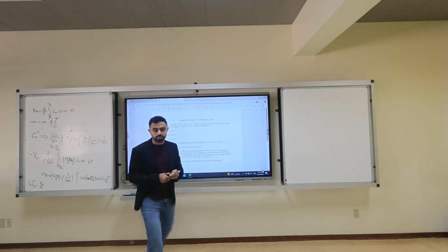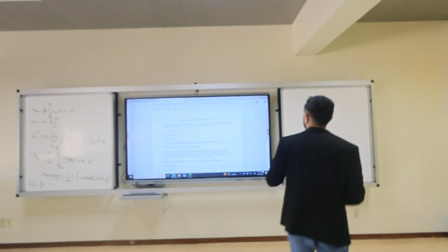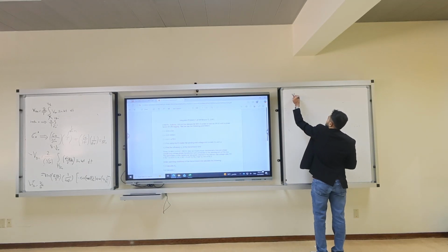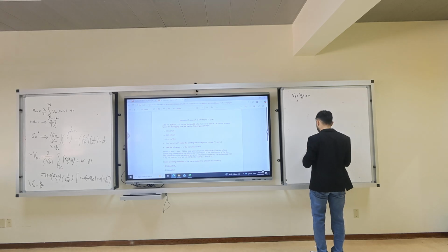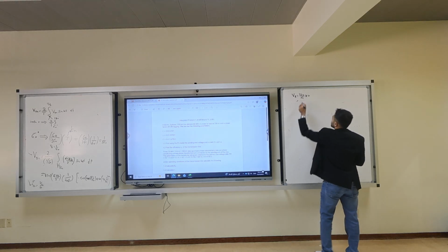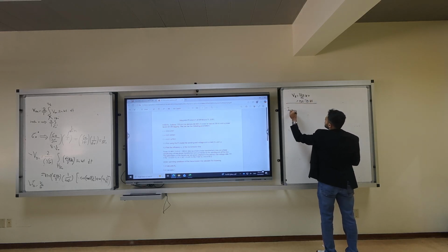So let's do it. Calculators. So what is VR? 230 over square root of 3 kilovolts, which is 132.79 kilovolt and 0. What is IR?